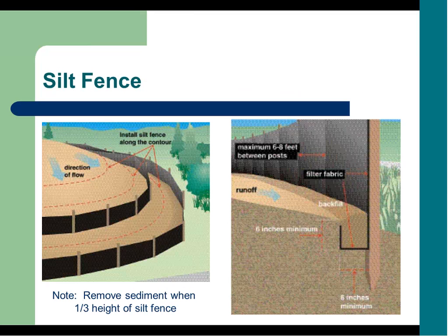Some examples of the proper way to install a silt fence. You always want to go perpendicular to flow, and you want to make sure you're creating that trench when you're installing the silt fence to make sure that it will, to the best of your ability, not just wash out when you get the force against it.